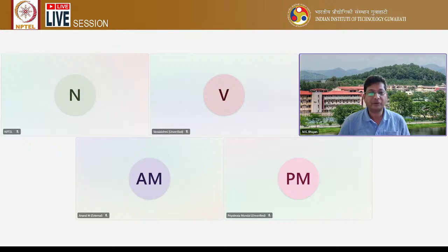And in the frequency domain also, how to consider the Fourier transformation. So first the image has to be multiplied by (-1)^(x+y). And after this, we have to determine the Fourier transformation. And after this, we have to consider the frequency response of the filters, the low pass filter, high pass filter, or the high boost filter. And after this, we have to do the multiplication, because convolution in the time domain is equivalent to multiplication in the frequency domain. So after doing the multiplication with the filter transfer function, we get the processed image.